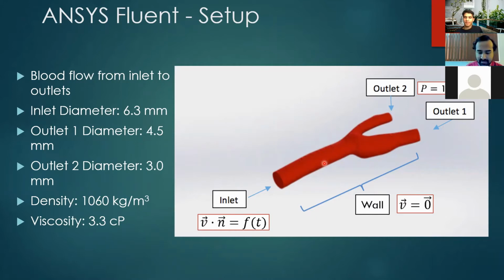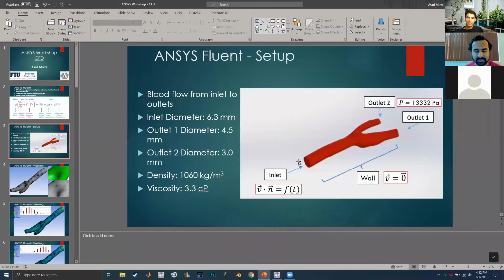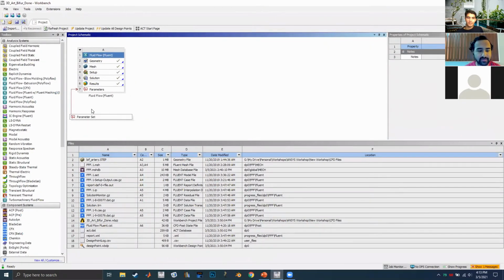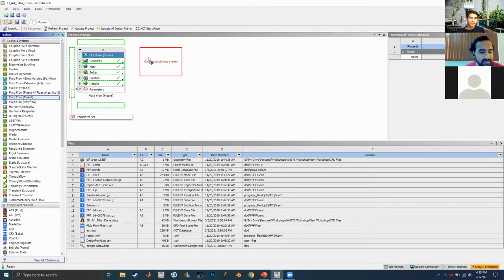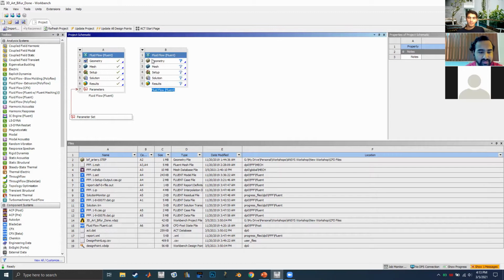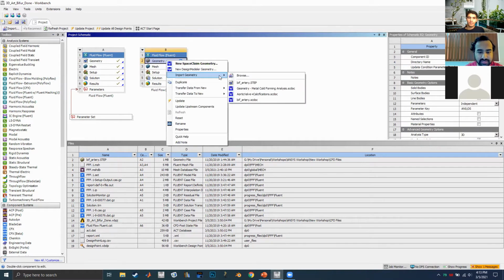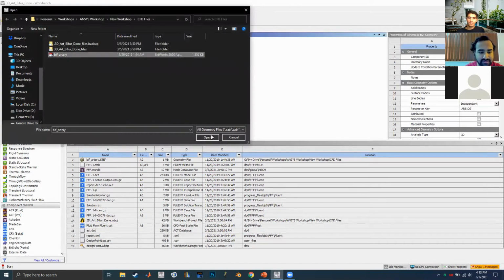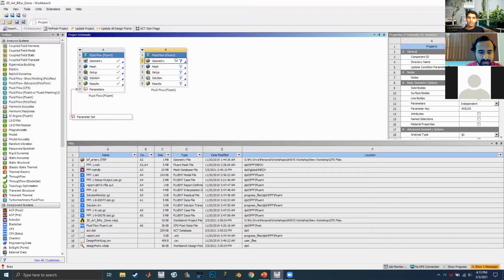No problem. All right. So let's go ahead and just jump straight into Ansys. Now, naturally, I've already done this before, so we have all of the results here. But starting from the beginning, what we're going to do is, instead of going for the static structural like we did yesterday, we're going to go up here to Fluid Flow and click Fluent. And that'll give us an equivalent little node setup here where we have to go from geometry to the mesh, to the setup, to the solution, to the results. So let's go ahead and attach our geometry. And it's the same one I showed in the picture. And I have it as a step file. So that's done.